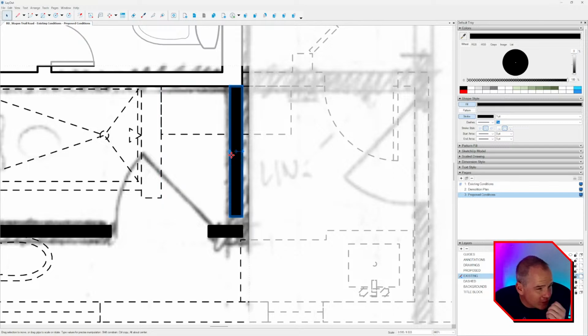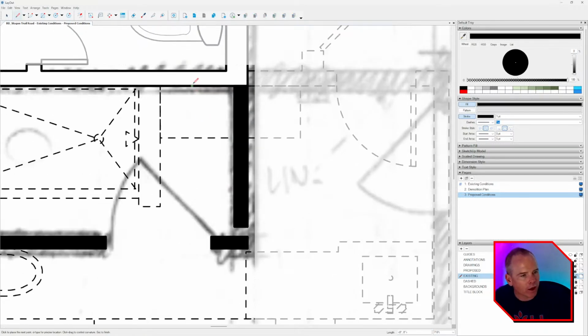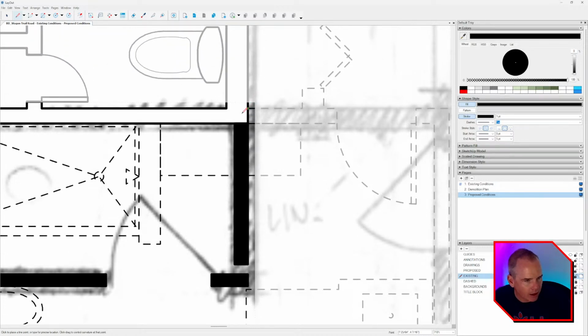I mean, this is where it's maybe questionable at this stage of design what I'm drafting, because the existing scan, technically that wall should be like 4.5, and it is. And I might have done that. This wall is at 6.5, being a plumbing wall. The reason this would be at 4.5 is because when we scanned it, it has the drywall on it, the gyp on it.